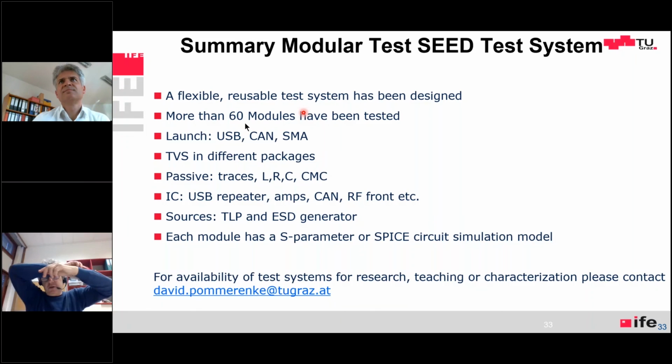Then the charge of this cable will go into the 50 ohm system, very nice, fast rise time, and so you can make a pulse which has double the electrical length of the cable you charge. That's called a transmission line pulser. It makes high voltage pulses. Of course, you could start at 5 volts, you can go up to 2000, 5000 volts. Rise times, you can go down to 40, 50 picoseconds in a very well controlled design. Many have like 200 picoseconds. That's a transmission line pulser.